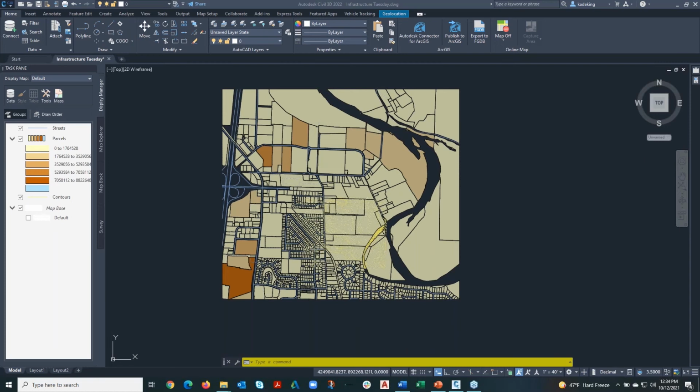I see some other questions that I'm going to come back to on contours. I see another question from Chris Brenton. He's asking, if you have a shapefile that is 100 megabytes when connecting, then what will the size of the CAD file be? It's actually just a link, almost like an XREF, okay? I hate to call it an XREF because it's not, but it's not embedded in the file. It's just a link to the data, so it's not going to increase the file size very much, which is what I really love about this. It's not going to be massive.